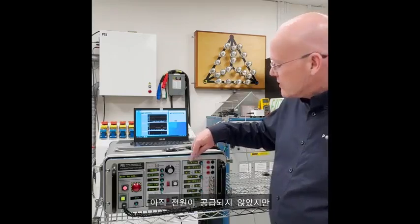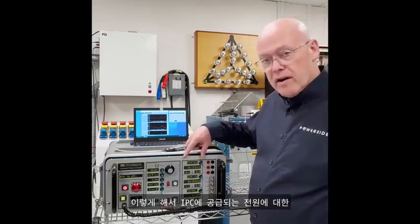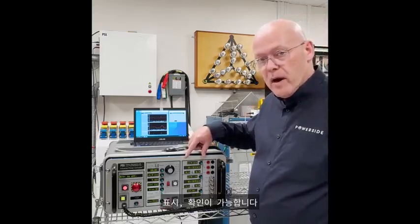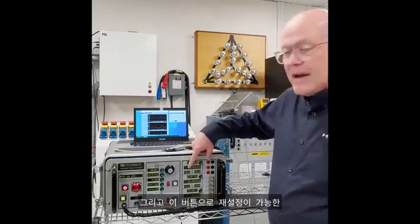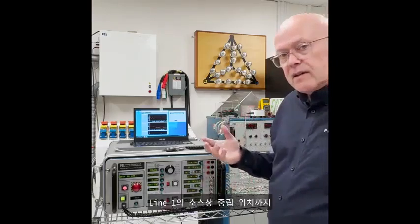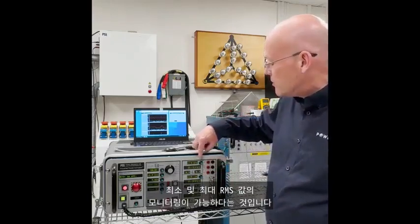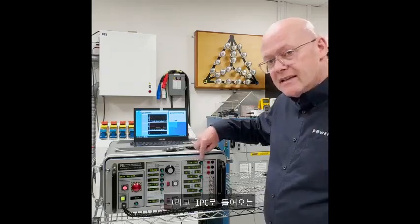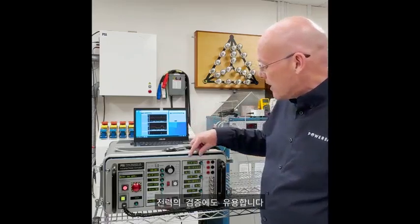We're not energized yet, but this gives you an indication or a verification of your power supply coming into the IPC. And what you have is minimum and maximum readings as well that you can reset with this button that actually monitor min and max RMS values for line 1 to neutral on the source. And it's handy to have this as a validation of your power supply coming to the IPC.